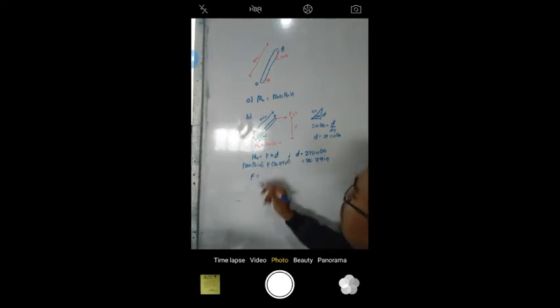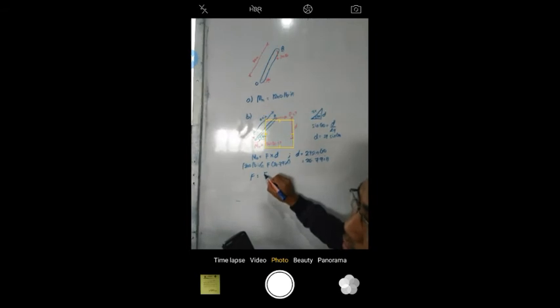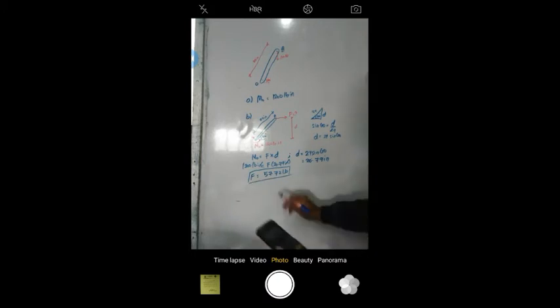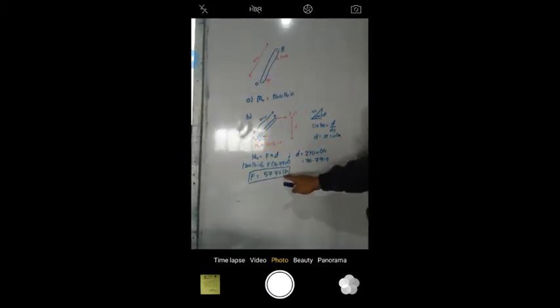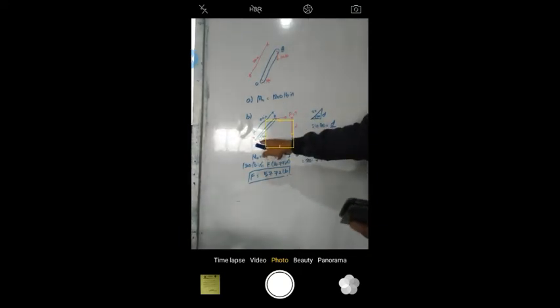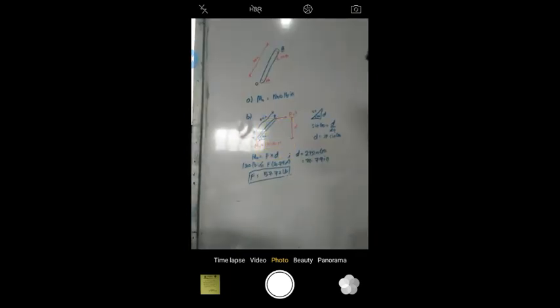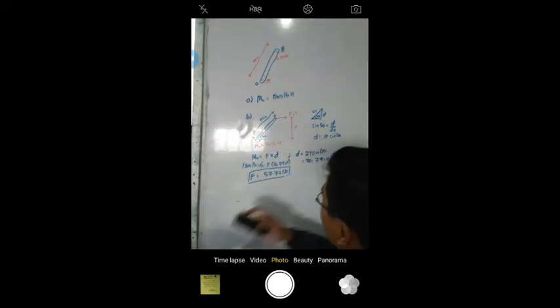So force is equal to 1,200 divided by 20.79. And that is 57.72 pounds. Okay? This means that this force is the horizontal force we need so that the moment here is the same as the moment we solved in letter A. Let's erase this.